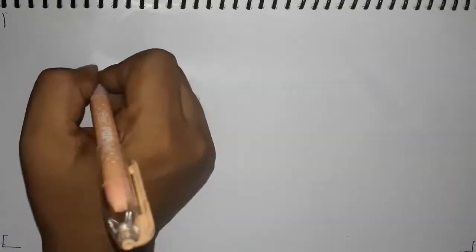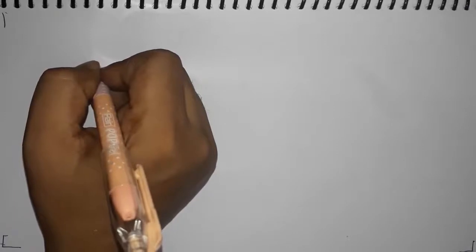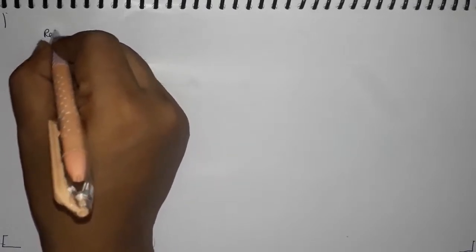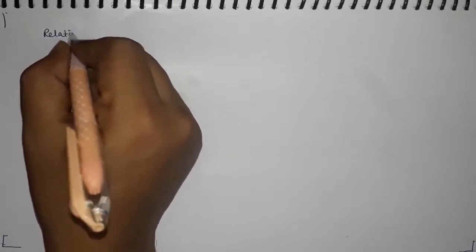So the pileup on barriers apart from those which are created by dislocation, for example Lomer-Cottrell barrier, happens at longer distances. Okay, so any barrier, for example precipitate, that can block the dislocation at a very long distance, and therefore these types of barriers are relatively temperature independent.